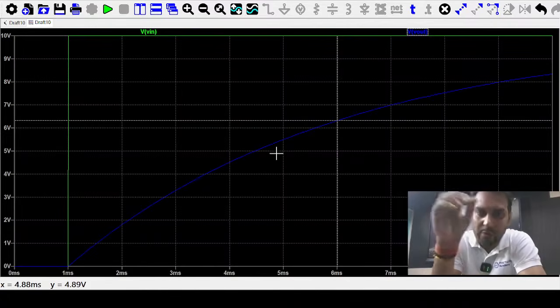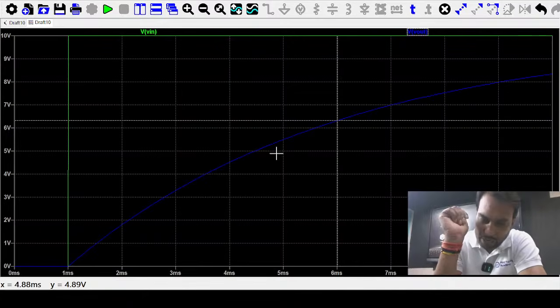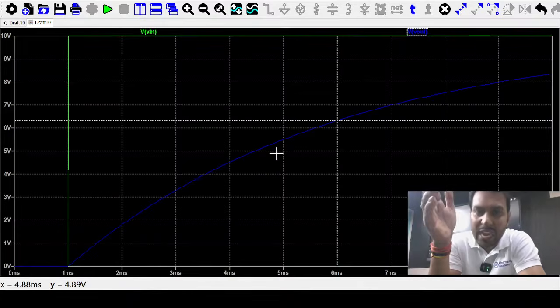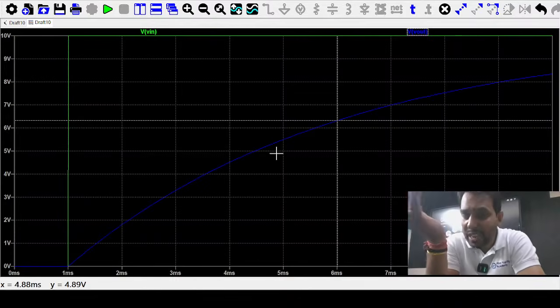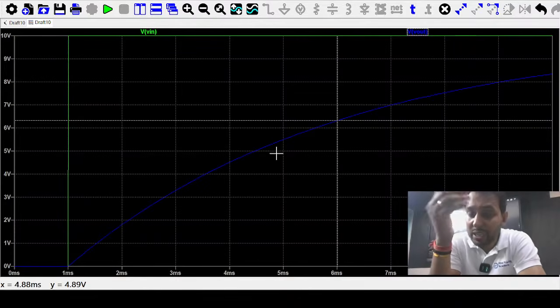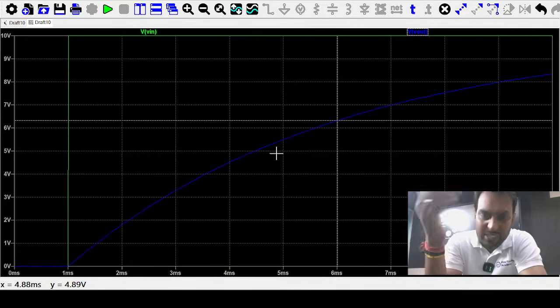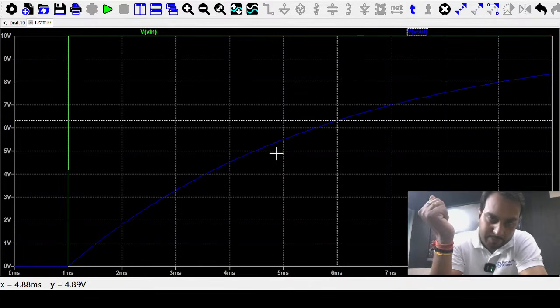If you are going for a precise way, the RC will not give a linear path, it gives a non-linear path. For charging time, if you are charging from 0 to 1 volt, for 0.5 volt it takes some time, but it is not equal for the discharging time, because this is an exponential charging or discharging, and this is a non-linear graph.